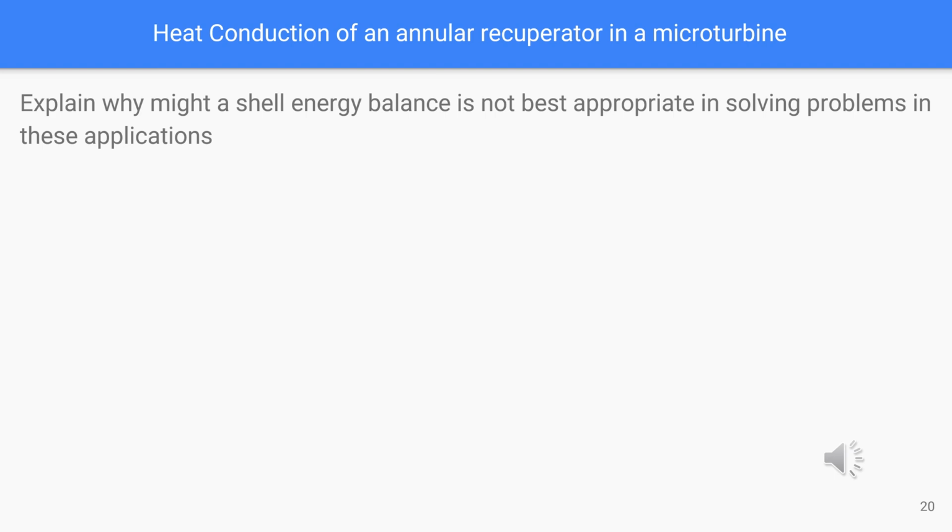Finally, the last question is conceptual. Why wouldn't the shell energy balance approach be appropriate for solving problems in these applications? Well, firstly, in gas turbines, air is typically turbulent. Shell energy balances are only appropriate for laminar flow problems.